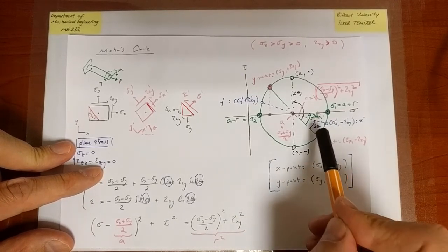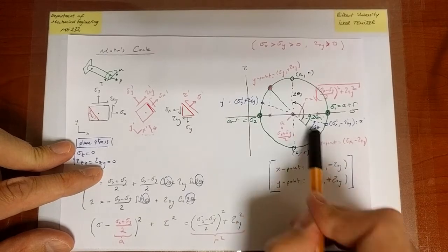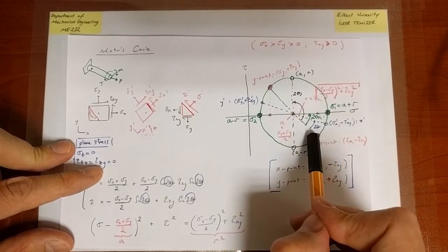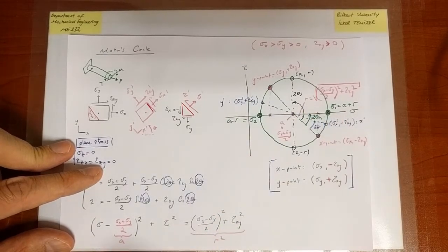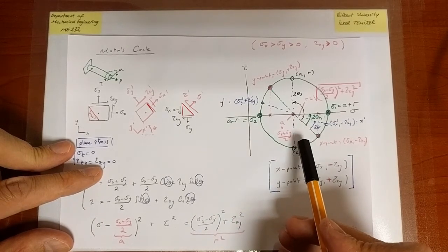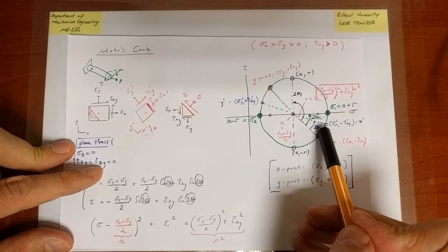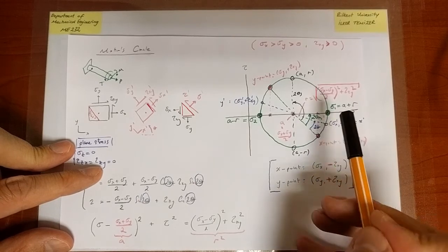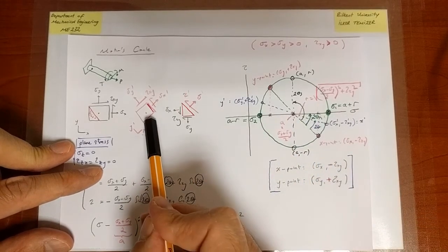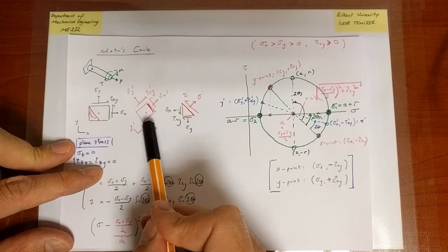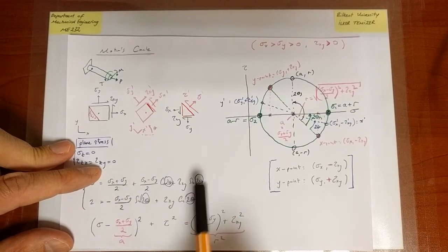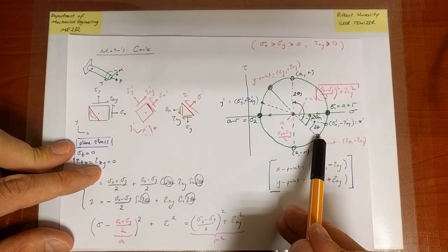You get this right, put them on your map correctly, draw your dial, identify the center and the radius, and then complete the circle. Everything else follows in a straightforward fashion. You just have to always remember that the amount of rotation on the Mohr circle is twice the rotation on the physical system. Okay? That follows from your equations. And everything we've drawn is consistent with that.